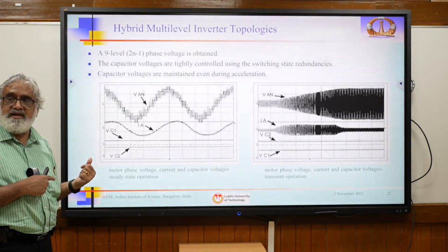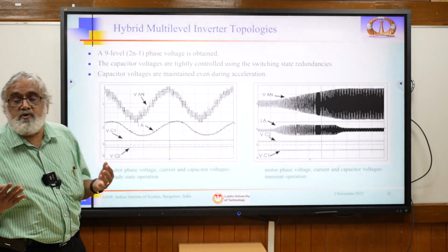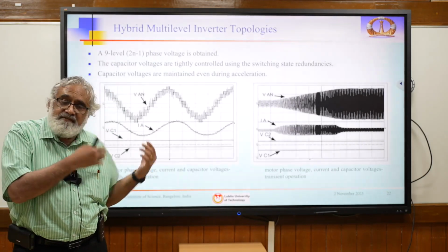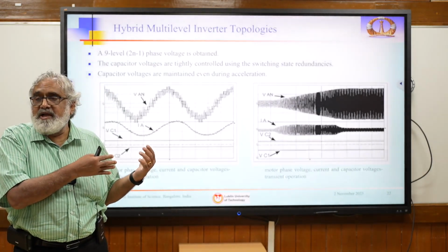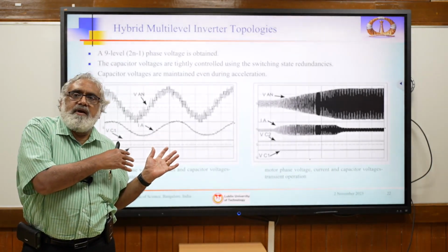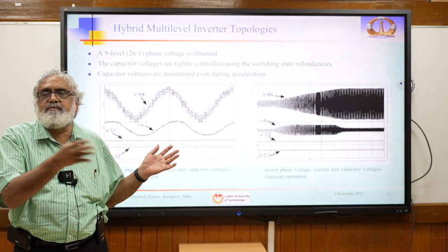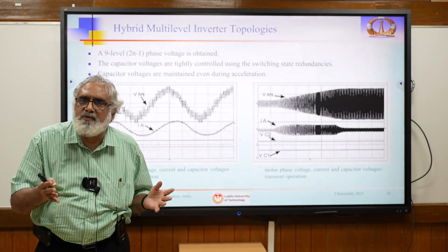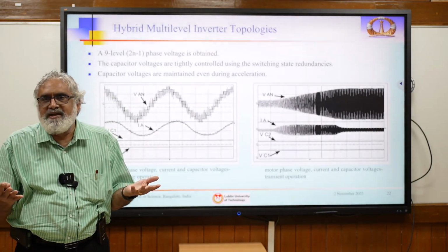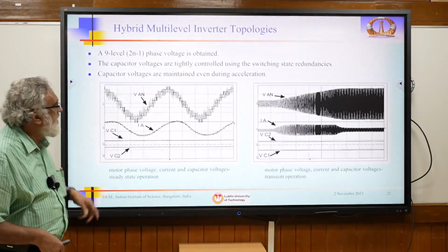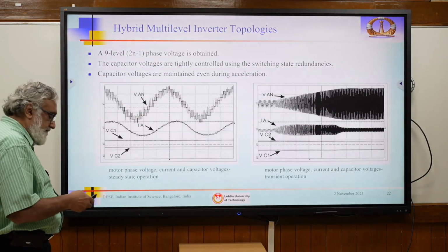What is the advantage of a single DC link? Four-quadrant operation is also possible if this DC link is replaced by a front end controlled rectifier. That means direct power flow from the mains. So back-to-back power flow is possible. Then we don't require a DC power supply. The power comes from the mains. The same converter can be replaced here.